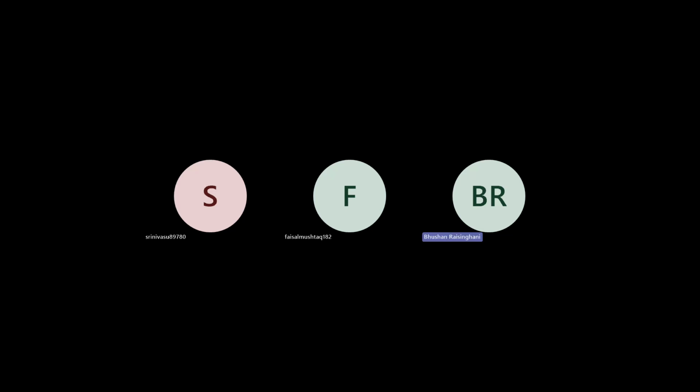And yes, only these aspect ratios are available for this particular case. And the height of the building versus the base dimension also is limited, so whether it is a flexible building or a shear building. So the behavior of the building is either shear. Shear is related to mostly the bending not being the governing design case. Mostly shear forces are governing, and hence the building is not acting as a cantilever.